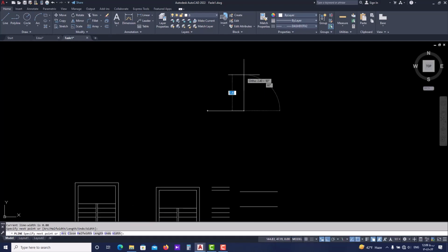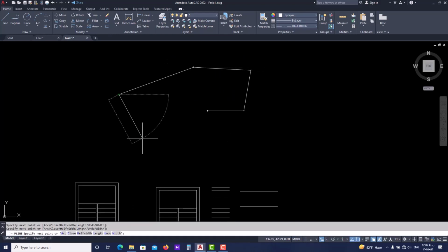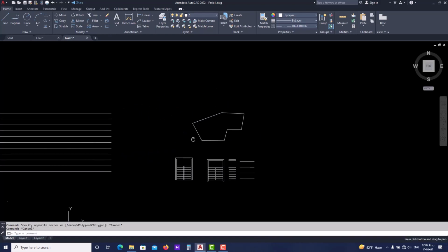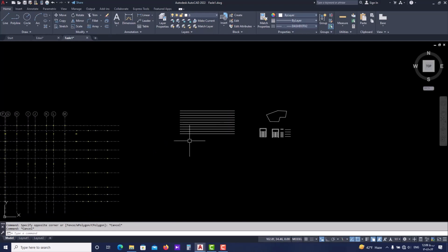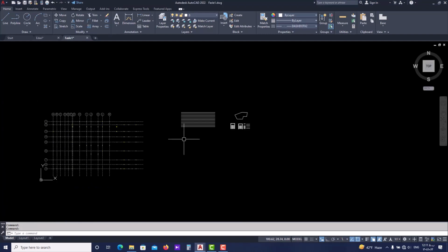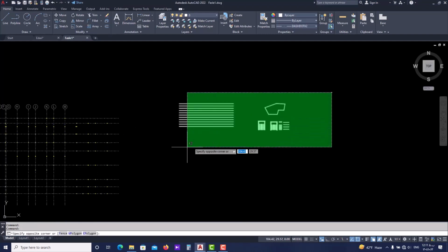For example, when we use polylines like this, we can easily create separation in one component's shapes, as what we have here. If you click on each line, they become separated. Now that we learned the commands, let's start drawing the walls in our plan. Okay, let's just remove these.